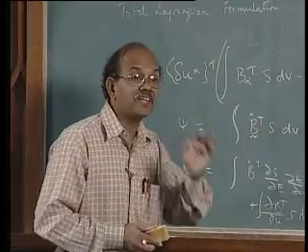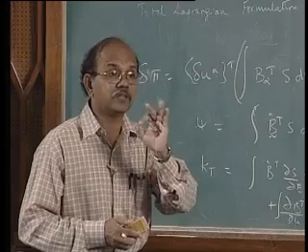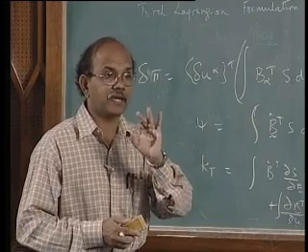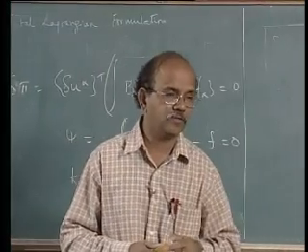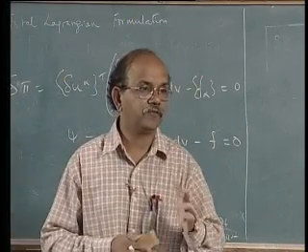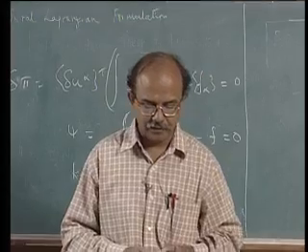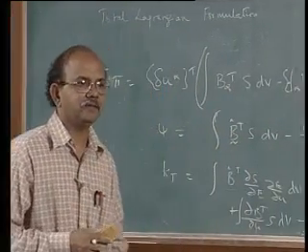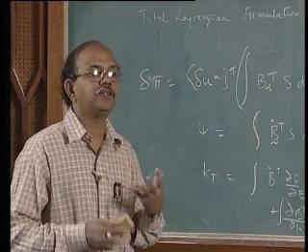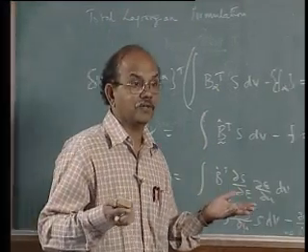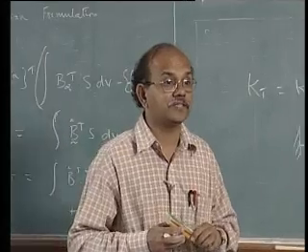What we do, term by term, I'm going to carefully transfer this to the current coordinate system. So let us take delta Eij, the first variation of Eij. Let us see how you can write that. Of course, what is it that is going to be useful to us when we transfer it? Deformation F, very good. Where are these kind of things that we did?